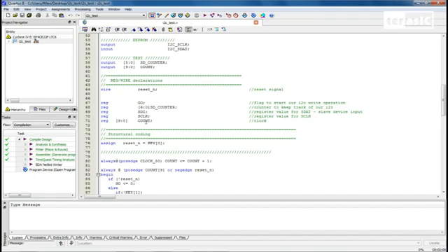Now the count itself is going to be our clock. Our EEPROM operates on a maximum frequency of 400 kilohertz, so we're going to have to slow down our clock considerably, given that it's 50 megahertz. So we'll move on to our structural coding.